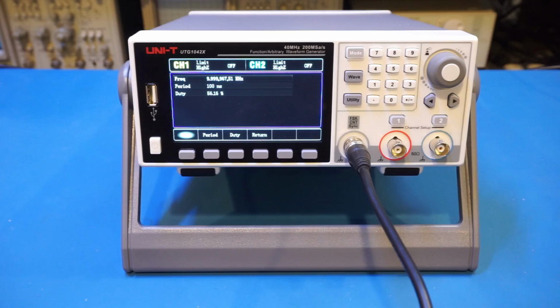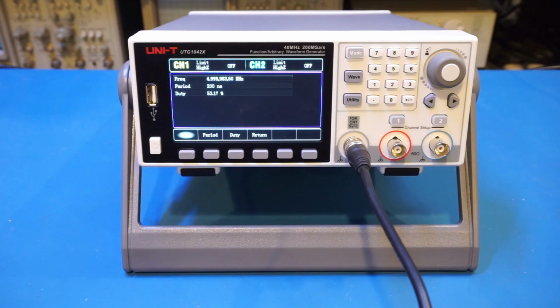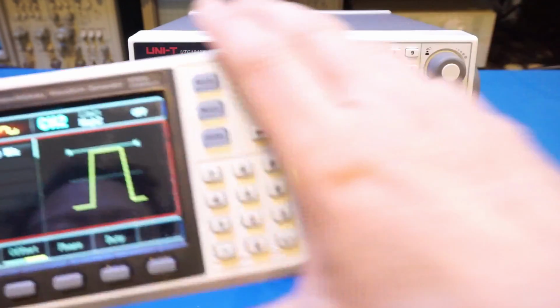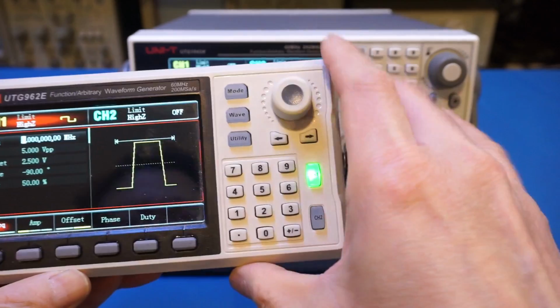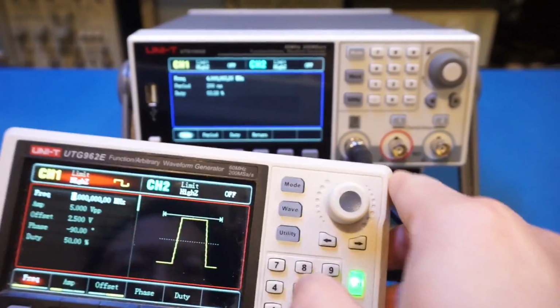Let me vary the input frequency, and you can see that. Let's do 9 megahertz, and you can see that we pick up the frequency with no problem. And as I pointed out, if it's not a TTL signal, unfortunately, you will not be able to capture the frequency here. So let me demonstrate that. For instance, right now the amplitude is 5 volts. Let's drop that.